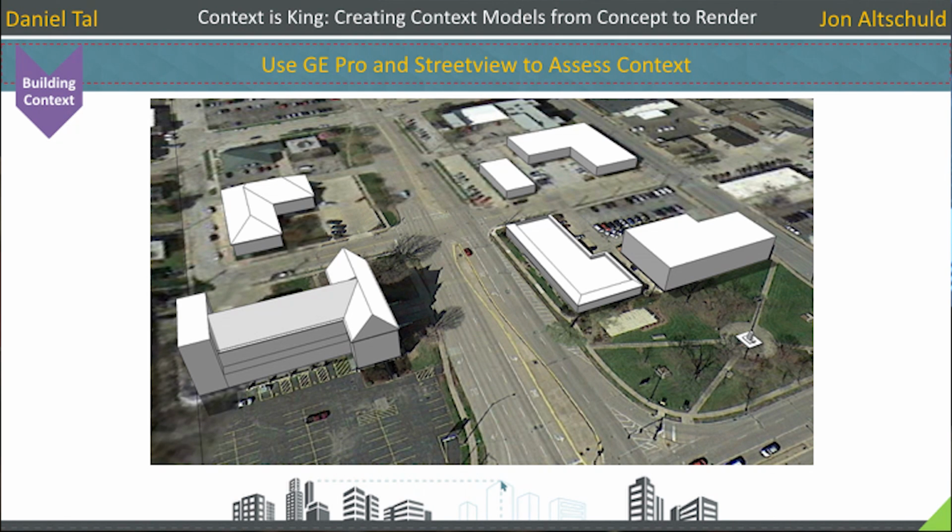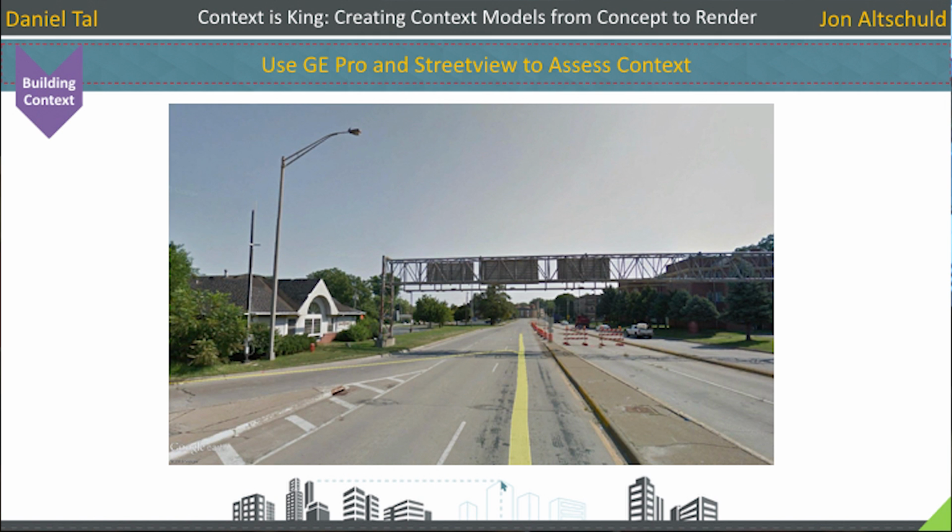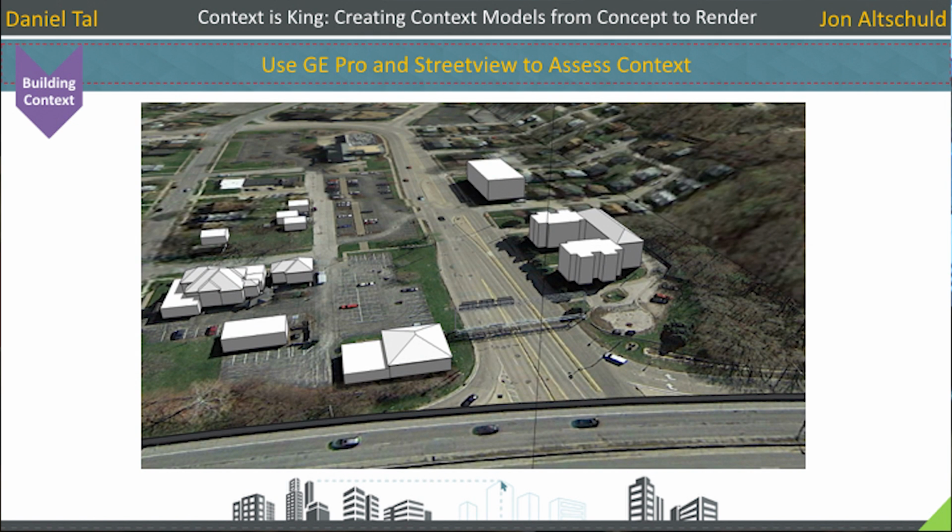Another, Dan already mentioned it, Vali Architects Instant Roof, which is part of the Instant Architecture scripts, can make roofs super quick, gets all of the details in there. Just one comment. If online, on the Extension Warehouse, anybody use 1001bit Tools ever? Yeah, there's an instant roof, a different version of instant roof or a roofing automation plug-in there as well. Yep, thank you. So then go back to your Street View, go back to your Google Earth Pro, take a look, see what's going on. You really quickly model the sides, model the roofs, get the detail in that you need. Again, use the context that you gathered in step 1 so that you can make this stuff really quick and easy.